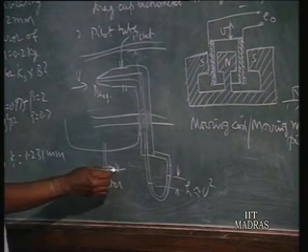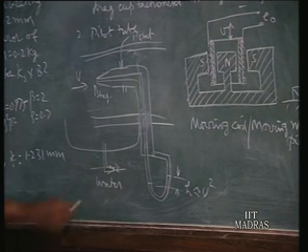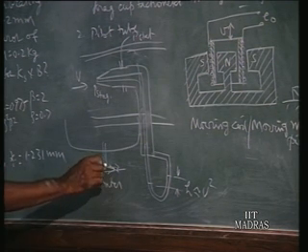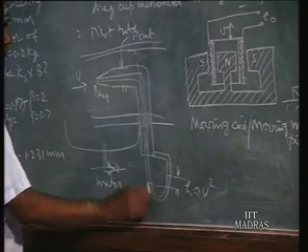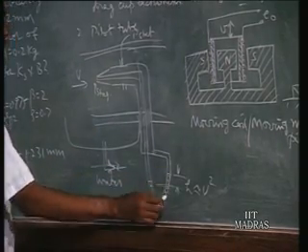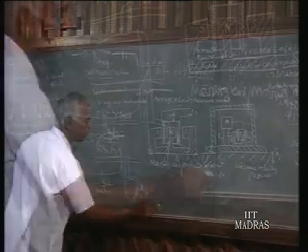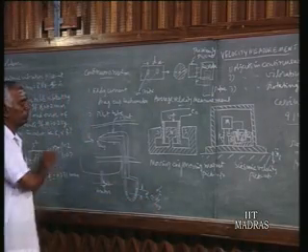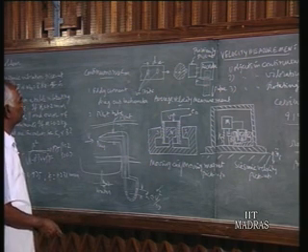So at the tip we will have both the static pressure plus velocity head, and the static pressure measured in perpendicular directions, and the difference between these two is shown as height, where probably you can have mercury. This head is proportional to V squared over 2g. So from there we find out the velocity with which the ship moves. This is the pitot tube.